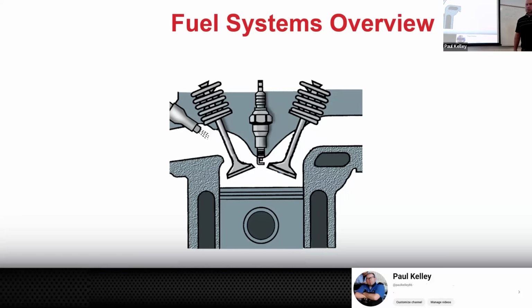If we start to get our minds straight, we've talked a lot about the piston and the cylinder and how it needs to make good compression, right? So if the cylinder is going to make a fire, a combustion stroke, a power stroke, it needs to have good compression, we agree, which means it needs to have the intake valve open at the right time and close at the right time. It needs to have the piston come down and build compression pretty sealed with the piston rings. It needs to have the exhaust valve sealed, but then after the combustion stroke, we need to have it opened and closed at the right time. We talked a lot about that in the first few lessons.